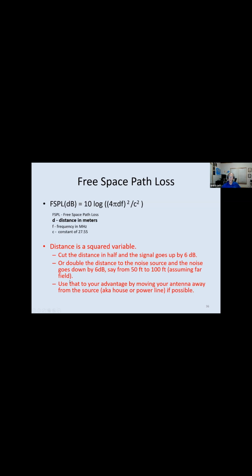I just went through this with a guy I'm assisting in Mississippi, where his end-fed half wave was in the front yard near the power lines, and he's in the process now of relocating that to the backyard where there are no power lines. He's got like 5 acres to work with. So keep them away from things that make noise. It's going to help you in the long run tremendously.